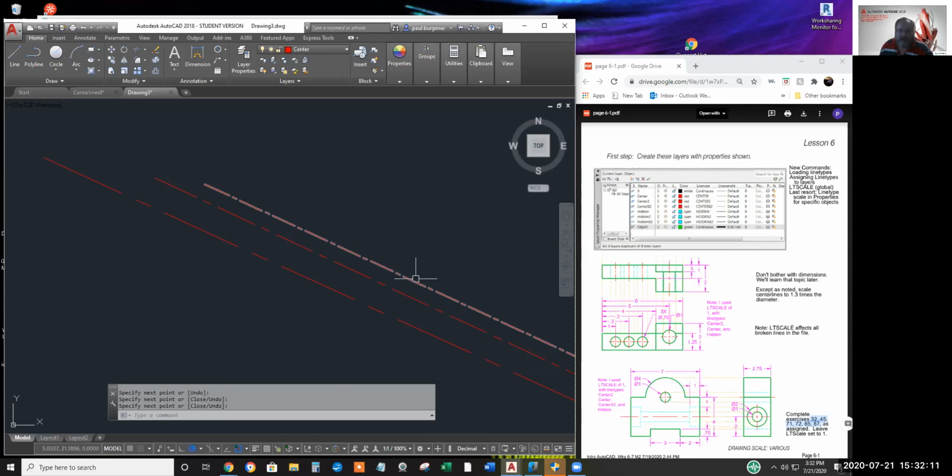How many short gaps are going to be in the given length of line? And if the line is on center X2 layer, there's few short lines. If it's on center layer, there's an average number. And if it's on center 2 layer, there's lots of short lines. So again, it's possible to use these line types as tape measures, but nobody does.